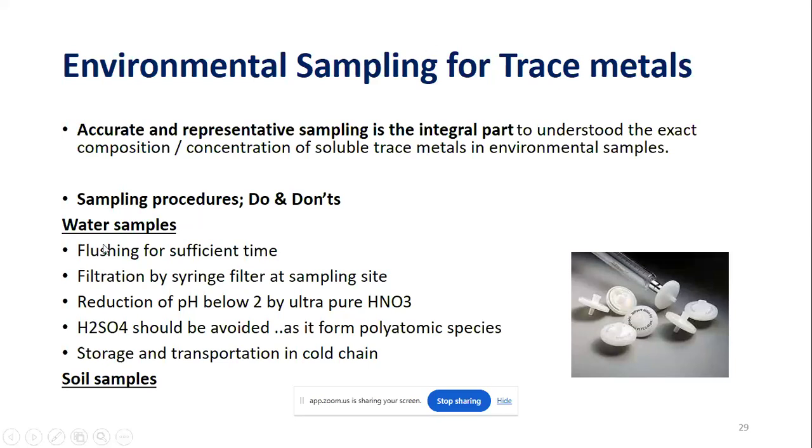So sampling procedures, I will not discuss here because it is probably not of use, but I would like to give one example of how the sampling would affect and why the sampling protocol is required. If I want to collect a water sample from a hand pump, for example, and I directly fetch the water and collect the water that comes first as a sample, then it could not be representative of the water quality of the bore well to which this hand pump is attached.